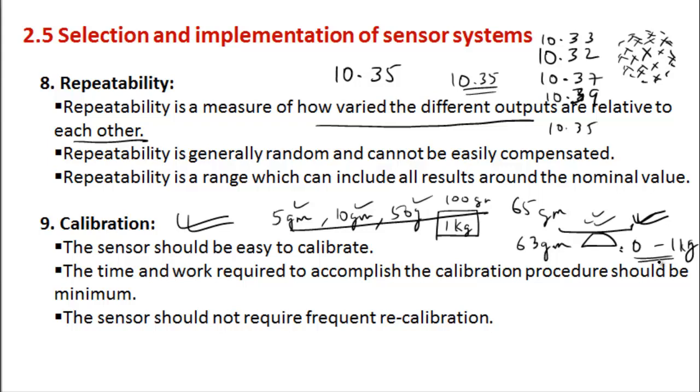Generally in any lab you go to, they will have a definite time span within which they do the calibration of the instrument. Calibration of robotic systems is also done at the industry level. If you have installed an industry level robot somewhere, at regular intervals you will have to keep recalibrating it so that it gives you accurate values.